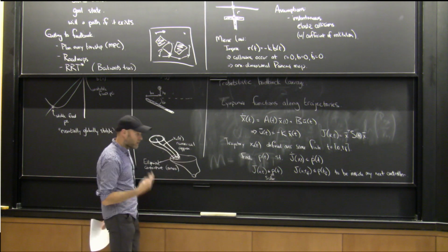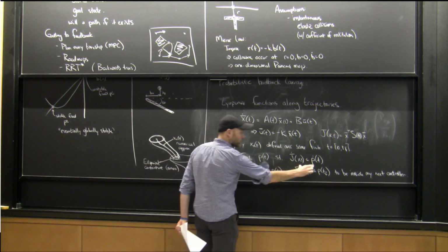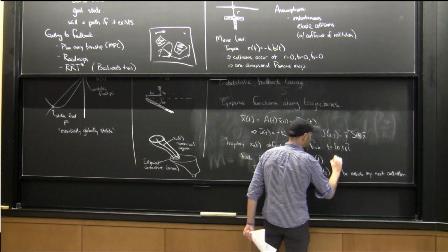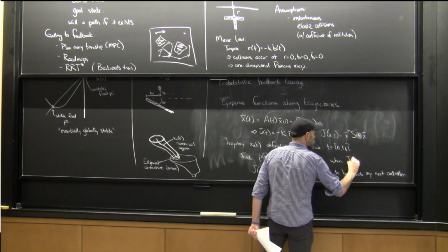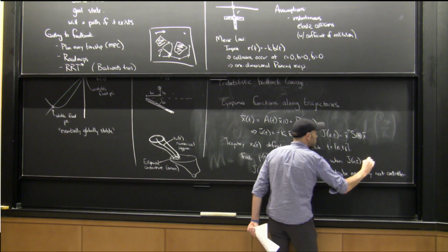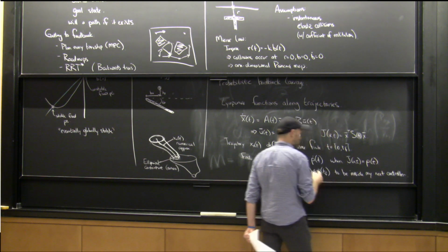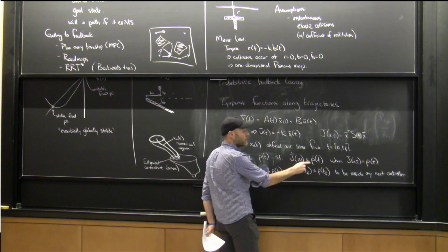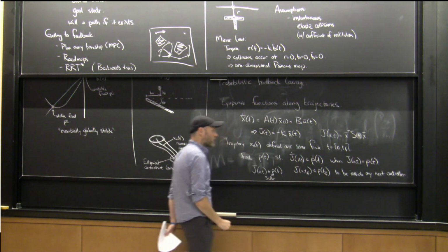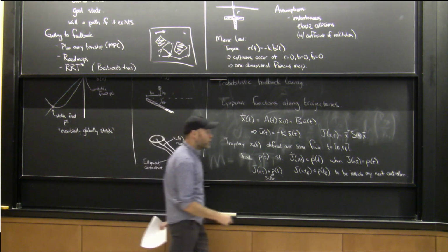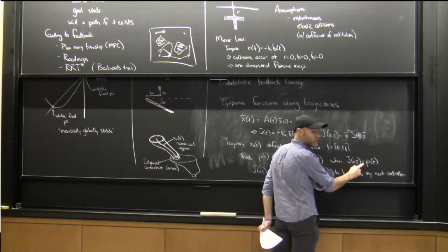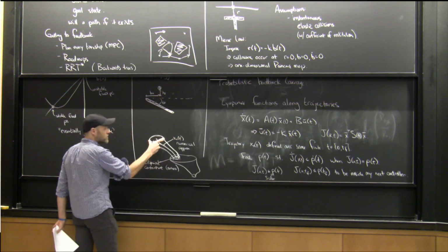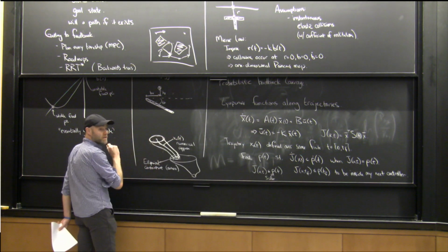My claim is, and with a little bit of thinking about it yourself, I think you'll be able to see, this is the condition that I want: when J of x, t equals rho of t, I need J dot to be less than rho dot, okay? Normally we say for all x less than or equal to rho, that would be saying I'd like to be a valid Lyapunov function everywhere inside the funnel.